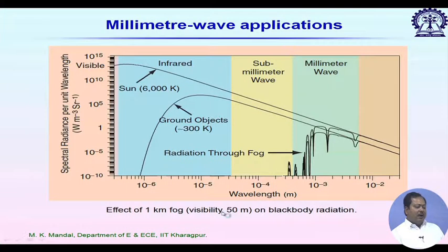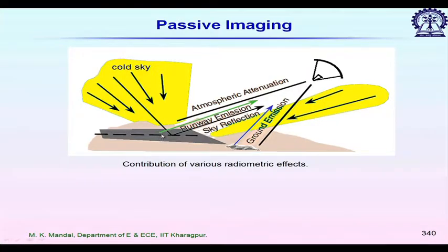So now going back to the previous one. Whatever power is being collected by this antenna depends on the physical temperature of the surface, the emissivity of the surface, and also the reflectivity, because it is also reflecting some of this downwelling radiation. Now, in practice, this radiation due to the cold sky is very small. So mainly the contribution due to the emission, or emissivity, is higher.